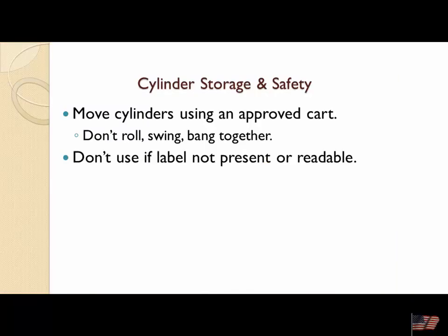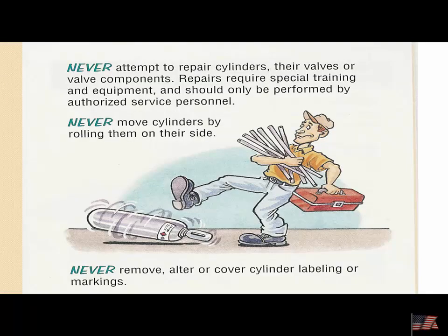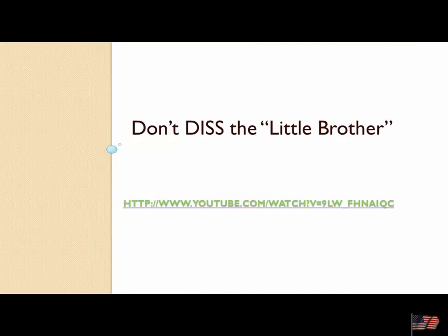Always move cylinders in an approved cart. Don't roll or swing or bang them together. And we talked about the label not being there. If you're ever there when the guy from the oxygen company comes and delivers them, I don't know how they do what they do, because he'll take two cylinders and he'll kick them and roll them. It's crazy. So never attempt to repair cylinders. Obviously, if there's damage for some reason, why the hell would you want to repair them?